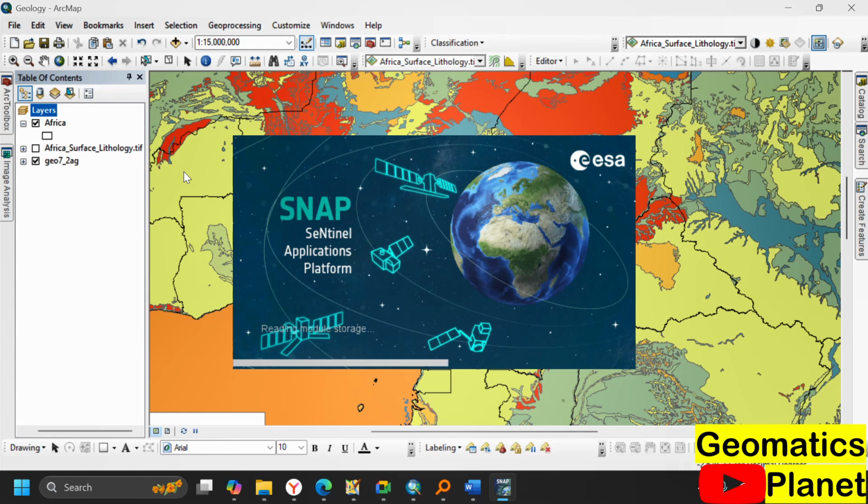Because for you to download and process Sentinel-1 data, if it is using your machine, you start downloading data and then do TOPS split, apply orbit file, and then do enhanced spectral diversity, create interferogram, then go into TOPS deburst, subset, multi-look, do filter and correction, then export and import to SNAPHU, and then from there you now start, maybe you want to generate elevation or displacement.